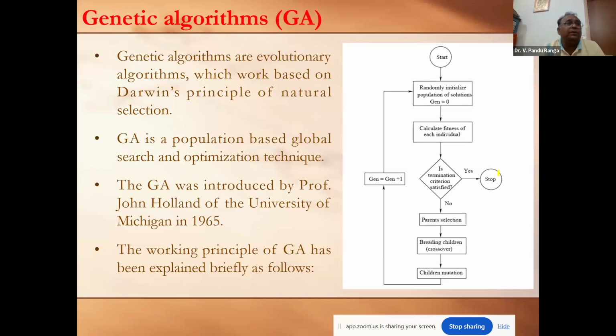That's why people generally say a neural network works like a black box. Whereas coming to fuzzy logic, as I said, the designer has certain knowledge about the process based on which it is taking a decision. Therefore, the success of the fuzzy logic controller purely depends upon how the designer designs the database and rule base of the system. If somebody does not know about the system and designs a fuzzy logic controller, it may not be effective. But if the same person designs a fuzzy logic controller after providing some training with the help of known data, it will be able to converge or provide some meaningful prediction.